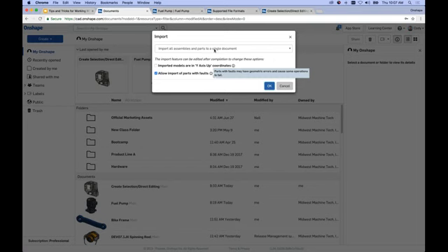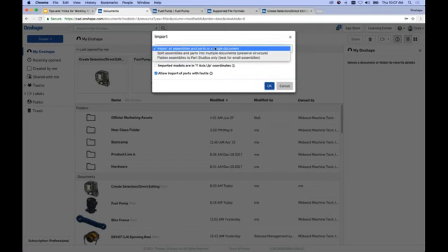So the last thing I want to mention about these is the import drop-down options. You should really only have to go into this if you have an extraordinary circumstance, I would say, and that is very big assemblies, or something that you want to deliberately flatten, so to speak. And I'll give you an example. The option here, split assemblies and parts into multiple documents, is great if you have a very big assembly and you want to take the existing hierarchy and structure and replicate that in Onshape, because it will create the necessary parts in different documents. Very useful for, again, very large assemblies.